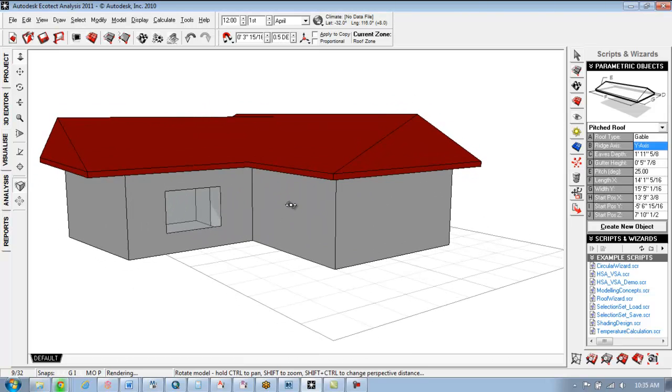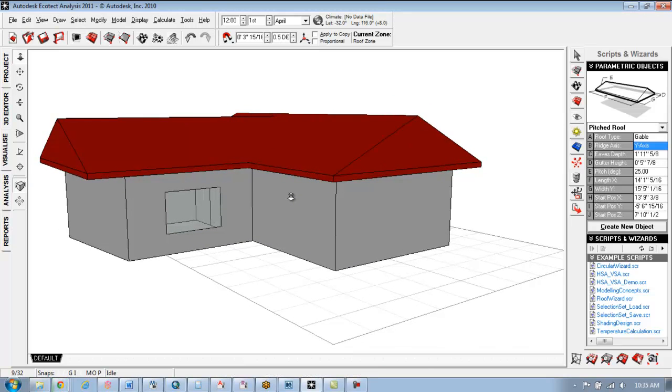Okay. Would you create a void in the other roof? Yeah. So make it like one roof. Yep. You'd have to do the same thing to actually combine them. Otherwise, right now this is just a roof that's adjacent to a roof. So if in your actual building you wanted it to be one open area, then you would have to void. Anytime you're combining two things that are zoned separately but need to be thought of as one object, then you need to separate them with a void. And it generally recognizes that pretty well.